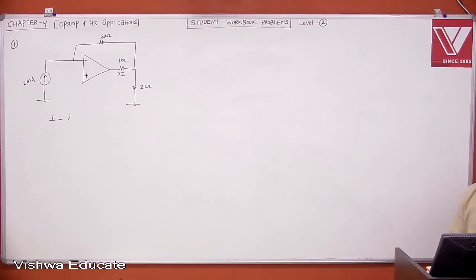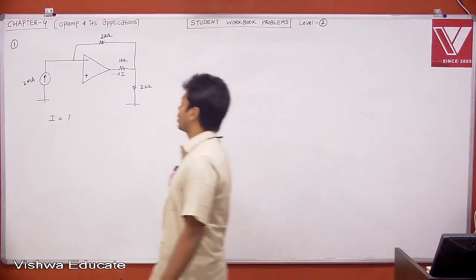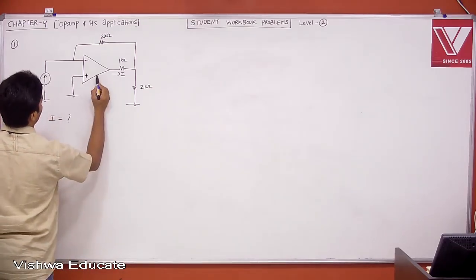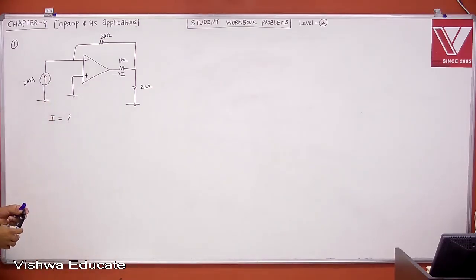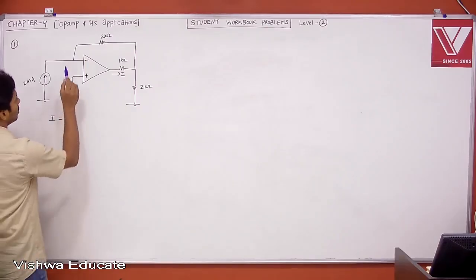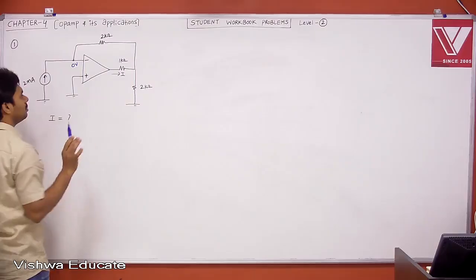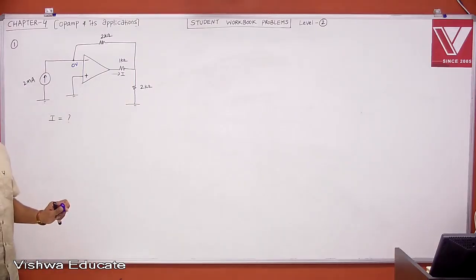What about plus? Is it floating? No. It is connected to ground. Now, negative feedback or positive feedback? Negative feedback. Virtual ground concept is valid? Yes. Remember blind techniques. 0, 0. Apply nodal analysis, you will get the answer. Simple. You will get the answer, no doubt. But you may need to apply two nodal analyses.